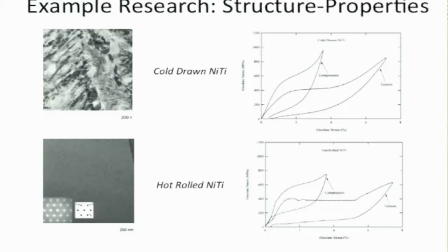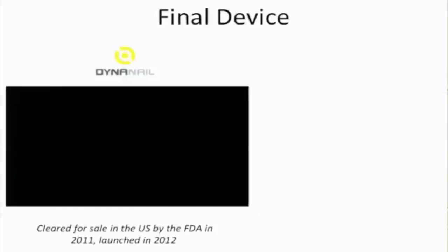And what we found was that it had the exact same properties, actually better properties than the other material people have been using up to date. The really exciting thing, if you know anything about precipitation hardened materials, is you can reversibly turn them on and off. So you can solutionize them, make them soft, work with them, and then reharden them. That's what we ended up doing with nitinols. We turned it into a material we could reharden. And that way we could make it machinable.